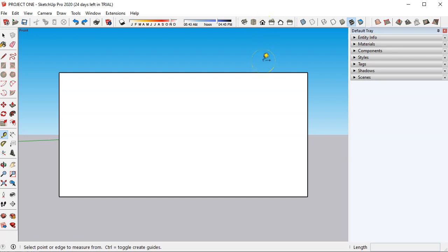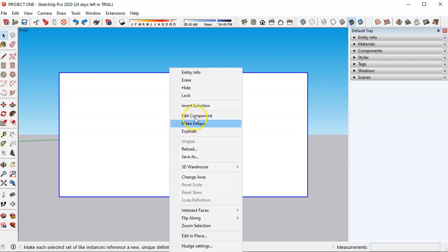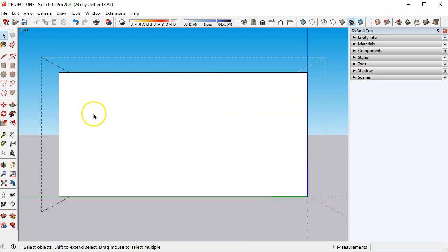So the next thing you want to do is to make sure you are drawing your guidelines and lines on this surface itself. If you select that surface, you're selecting the base house component, which is made up of 3 other components: the walls, floor, and the ceiling. We have to edit that. And now we're looking at the walls, but we still can't draw on them because we have to edit this component. So I'm going to select that again, right click, and edit the walls component.